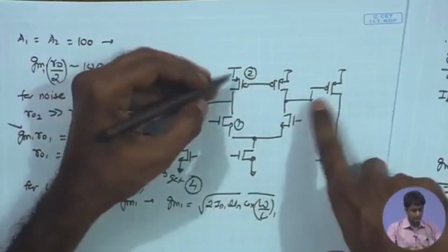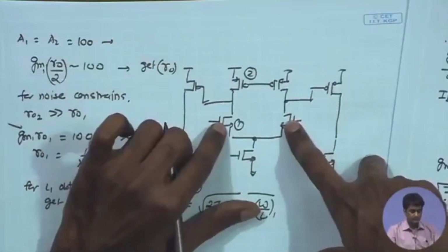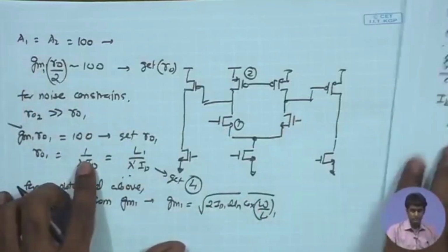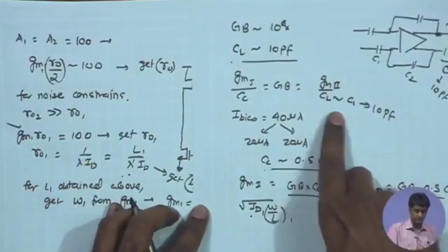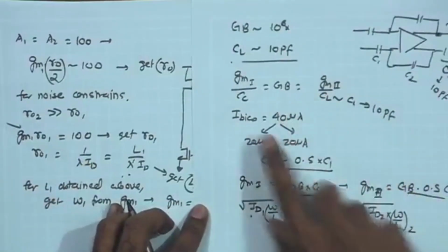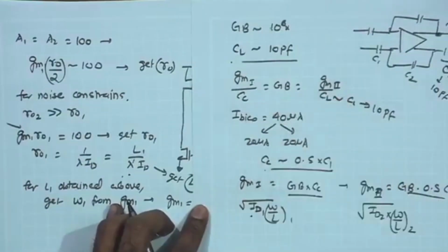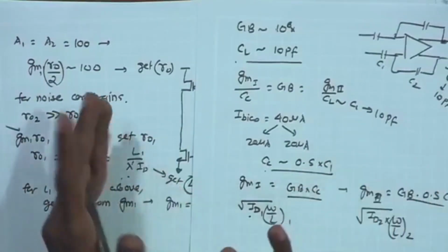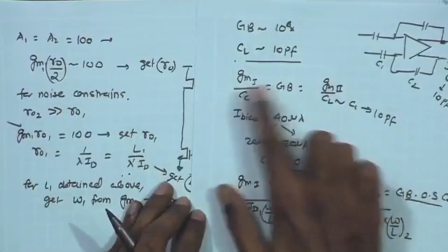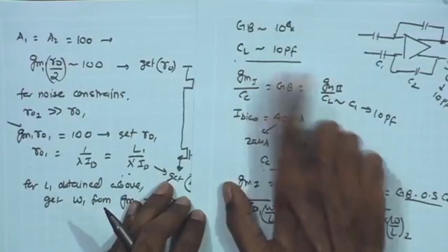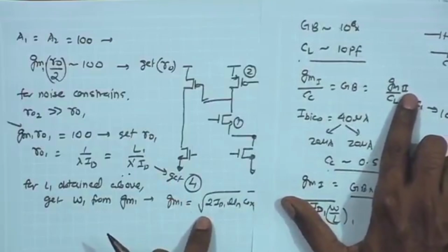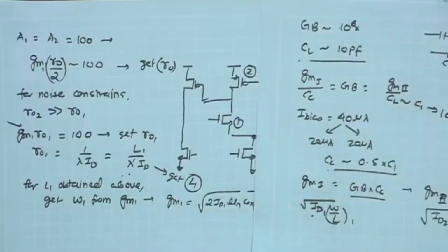Now, likewise, if I have the value of GM1 and also the GM2 known from the previous step, if you recall, the GM1 GM2 ratio also was known depending upon the CC CL ratio that we set. So, the CC CL ratio was determined based on area constraints, and based on that I determined the ratio of GM1 to GM2. GM1 is known, GM2 is now also known, and therefore I have the current budget. I also have the current budget given to me.